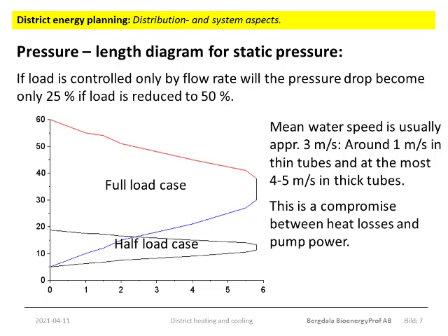To avoid too high pump power demand, you will normally select pipe diameters so that the speed of the water in the main distribution pipes is no higher than some 4 to 5 meters per second. That is for the main, the thickest, the biggest pipes. They can be anything from 500 to 1500 millimeters in diameter. The pipes extending to individual customers may be as thin as some 20 to 25 millimeters. And in these thin pipes you want the water to travel slower.